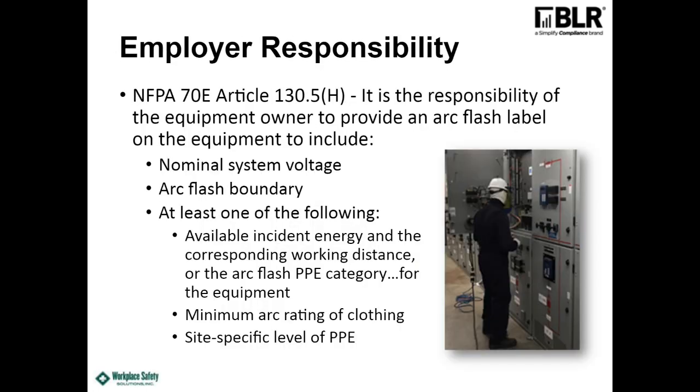This is the responsibility of the employer. This is a section that a lot of people don't realize. So the employer sometimes will say, well, we're not going to go in the main switchgear or the bus duct or things that we suspect have higher arc flash levels based on NFPA tables. We're going to hire contractors for that. So they assume that the contractor knows what levels they're going to have. But they don't. How would they? They need to know a lot of information from your system before that can be determined. And that's where the engineering study comes into play.